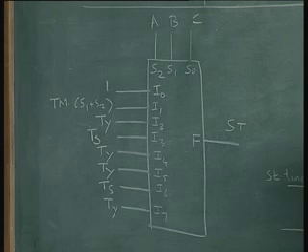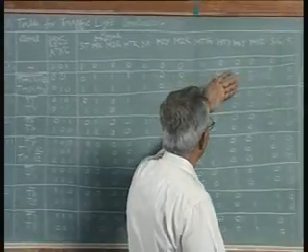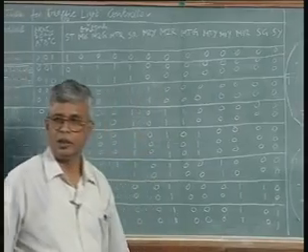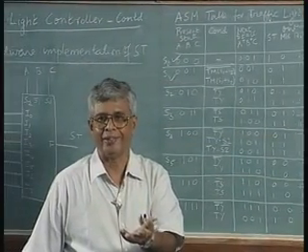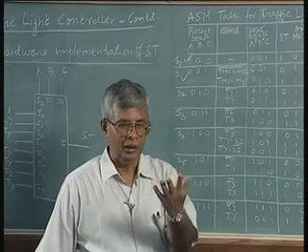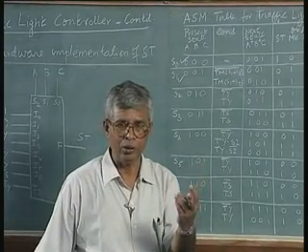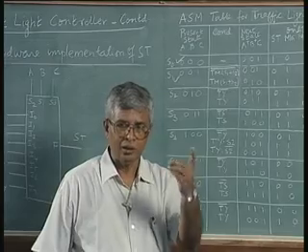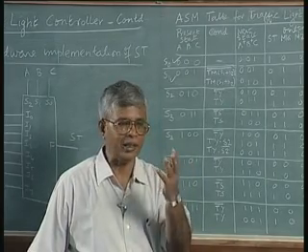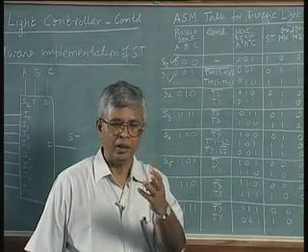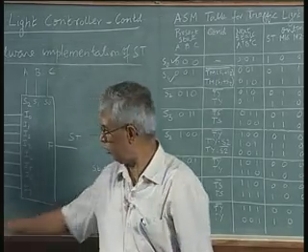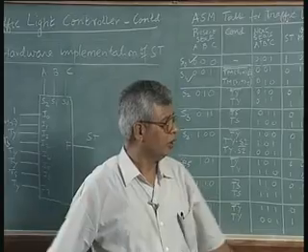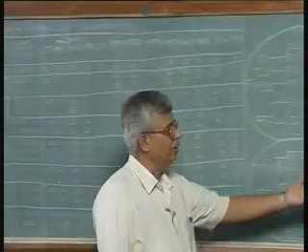So all other outputs, there are 13 of them I guess, 1, 2, 3, 4, 5, 6, 7, 8, 9, 10, 11, 12, 13. There are 13 outputs, one is there. All other 12 outputs correspond to 4 lights. There are only 4 lights, is it not? Main 1, main 2, main turn, side. 4 lights, each light has a green, yellow, red. So 4 times 3, 12 lights. Start time is the 13th signal I already showed here. The 12 lights are very easily written here.